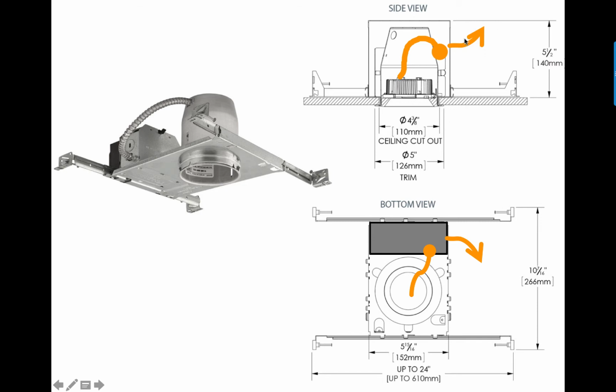When you do what's called remotely switching a fixture, you draw this little arrow here. It's called a home run. And it just indicates that wire goes somewhere, but it's outside of the drawing. And here's the, I guess, plan view, bottom view, which is the kind of puck-shaped light source, the LED heatsink. Above it, a wire goes to the junction box. That junction box is this box here. And then it goes away, goes home.